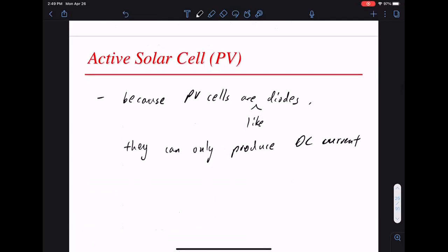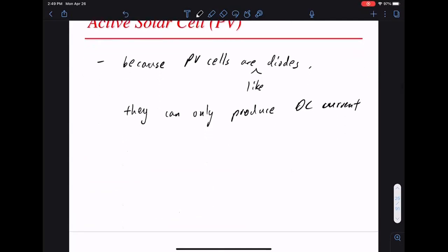So the picture we have, before going to the circuits and writing down a lot of equations, is a circuit built up from a current source. This current source comes from the solar energy: because photons can excite electrons, we have a current source. This circuit will also have a diode in it, because of the PN junction.